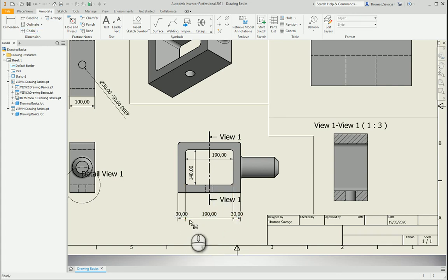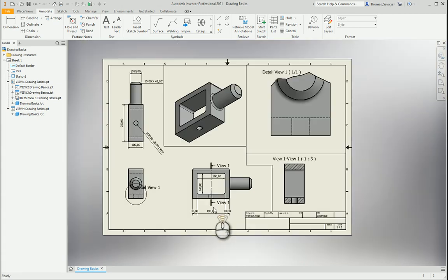So this one just dimensions in between the lines you select, which is very useful, because if I was going to dimension the width of these two, the width of the hole, the cutout that we're going to do, then back to the width of the end of the block, I'd do 1 dimension, 2 dimension, 3 dimensions. Whereas that is just 4 clicks, right click, create, done. So that's really useful. What else?